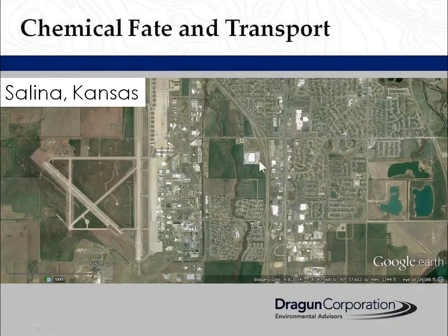There is significant groundwater contamination and soil contamination here, and also a very complex geology. If we look at this highway from the west side of that, it's dominated by low permeability soils that are mainly where diffusion would be important, but there are some permeable zones. And when you get to the east side, it's dominantly high permeability materials. But in trying to clean up the chemicals in this area, it's very important to understand that diffusion is a big component.